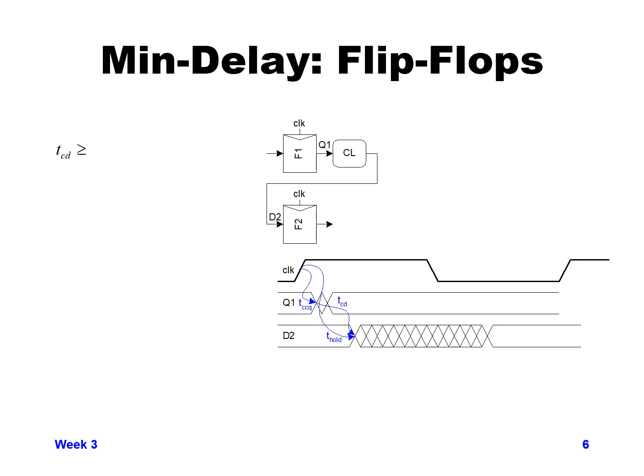If our clock goes high, we have a contamination delay from clock of F1 through to Q1, and that's the fastest the data can make it through F1. That value of Q1 goes through the combinational logic to get to D2. There's a fastest path through that combinational logic to get to D2, which is your contamination delay T sub CD of your data.